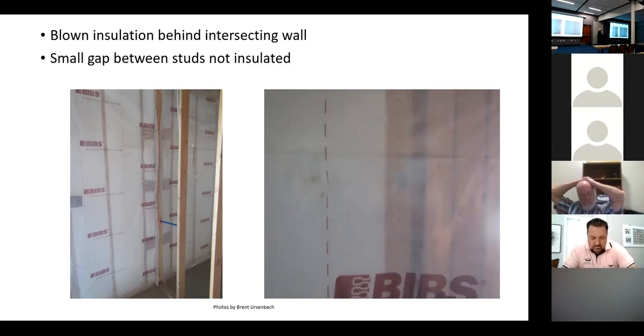And it works really, it's a pretty good system, but the big problem I think comes from, and this is just my assumption, I haven't done a scientific study on it, these ceilings are all full of can lights, and they're supposed to be airtight can lights, but they're not 100% airtight. They leak enough that we're getting moisture in through the can lights for the most part. So we didn't allow them anymore when I left. I don't know if they do now, but that's our experience with them.